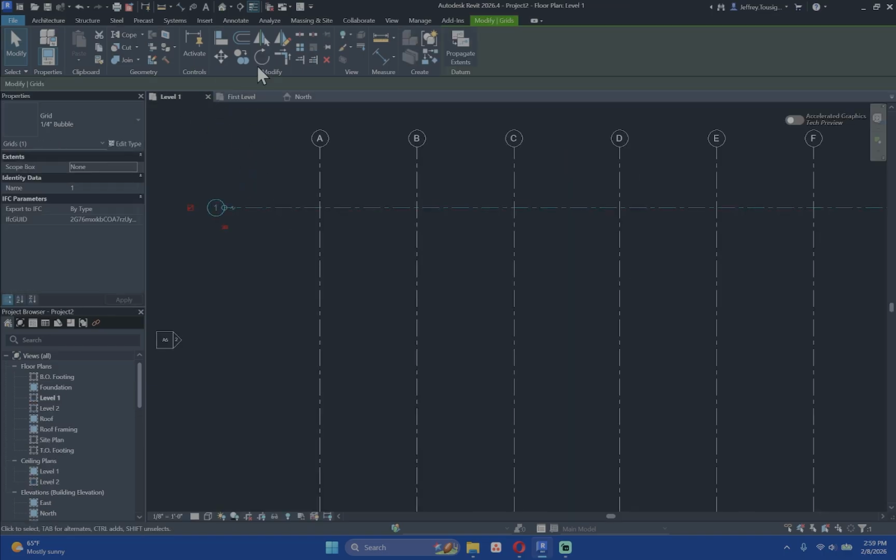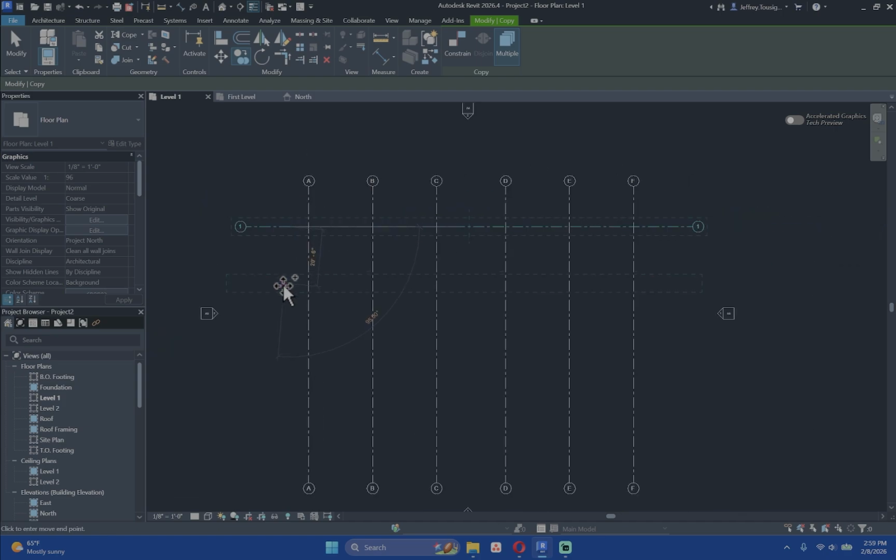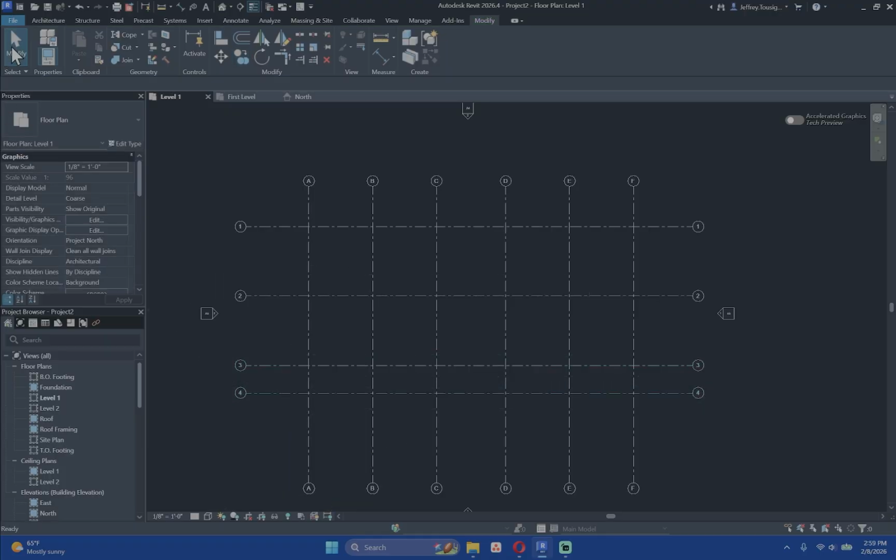If you didn't have these grids or if you didn't have dimensions, you can still draw them out, proposed based on the size of your building. I would just probably focus more on drawing out the building at that point, and then going back and drawing grids likely based on where the architecture of the building would be. In this case, we're being provided grids. Maybe we've already started talking with the structural engineer, so we are good.